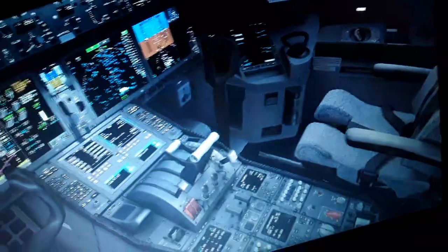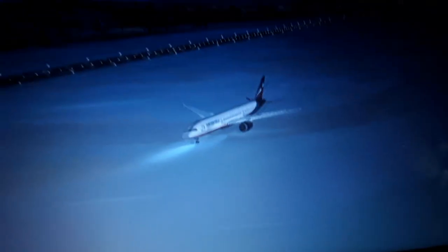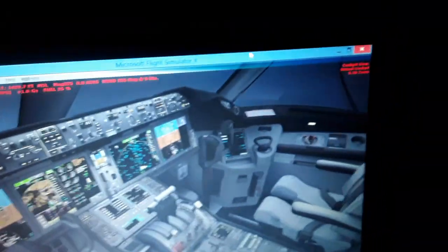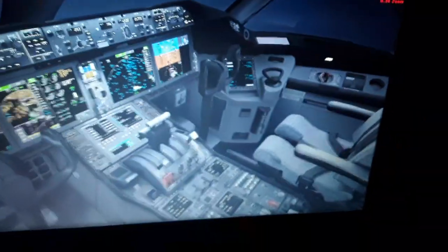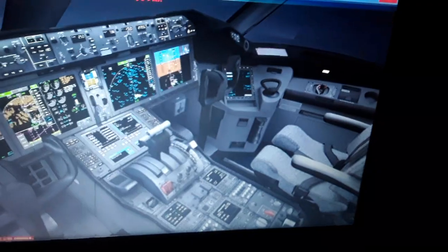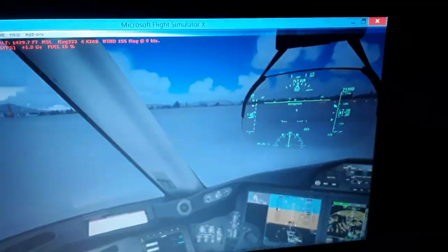So we set the flaps for takeoff, and we're gonna have the takeoff here. So we're gonna have now the takeoff. Thank you for watching until now. We're gonna start now the flight of the aircraft. We taxi into the runway. Everything is complete, so we advance the thrust levers forward and disconnect the parking brakes and use the tiller, as you can see.